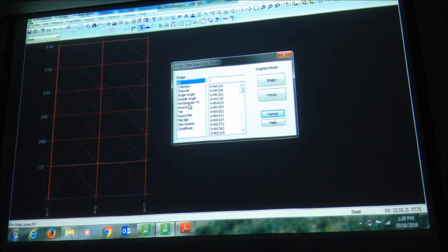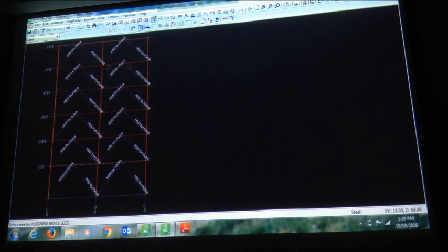And as I said, I will use a rectangle HSS section, maybe a 10 by 10, the thickest one. 10 by 10 by 3/4 is kind of that thick. This is heavier than your 18 by something. I'll give this one just to make sure that my braces will work. I defined it, it's not showing, but how can I see that? Click on this button, it shows me that.